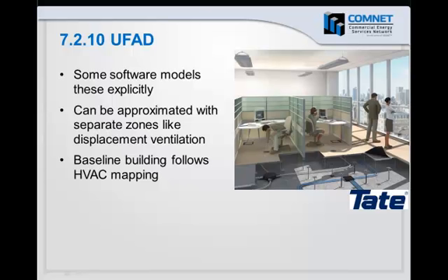Then underfloor air distribution is another topic. These also can be modeled explicitly by some software applications. They can also, like displacement ventilation, have some stratification in the space, which can be approximated by modeling the room in separate zones. The baseline building follows the HVAC mapping procedures.